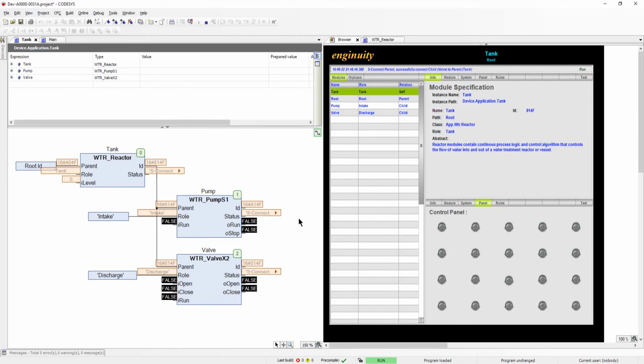And then when we select a module, the module would have to tell the HMI, giving a list of views that it's able to access and communicate with, and load up the additional tab buttons with those selections. Then when you click on the button, it would simply copy the file name and location into the frame, and then the frame would display that screen.